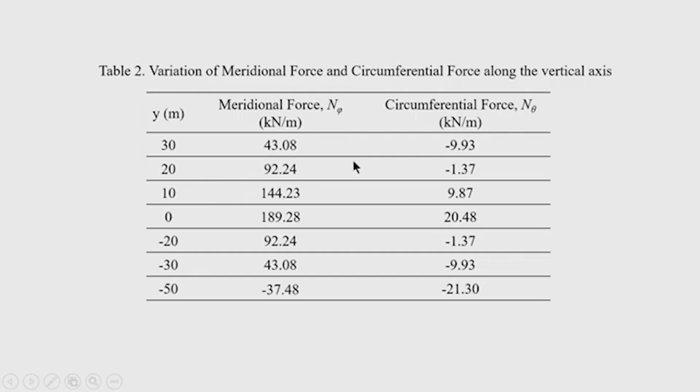So, the requirement of reinforcement and checking the adequacy of the thickness of the shell, so that the induced compressive stress remains within the permissible limit, that type of problem I have earlier demonstrated in case of spherical dome. So, the same principle can be used here to check the safety of the shell in regard to its thickness and also to specify the reinforcement requirement in the shell.